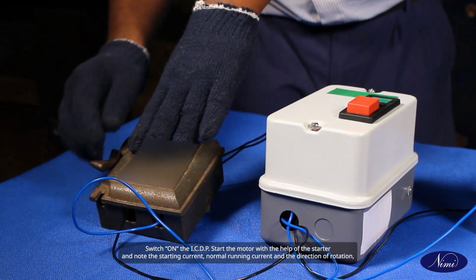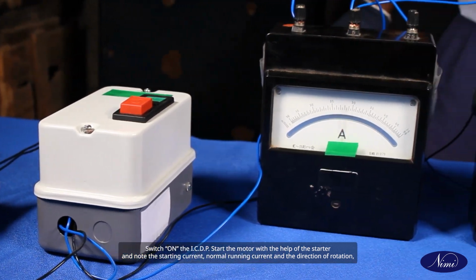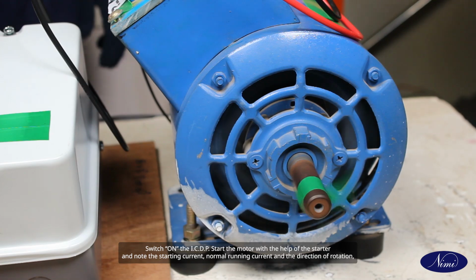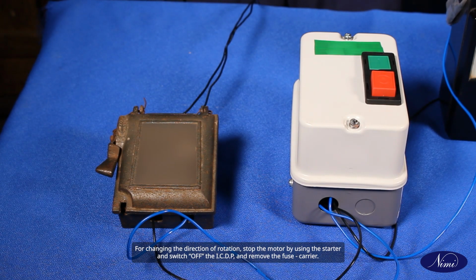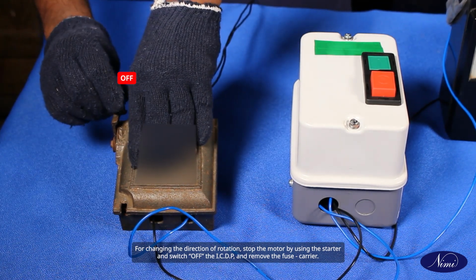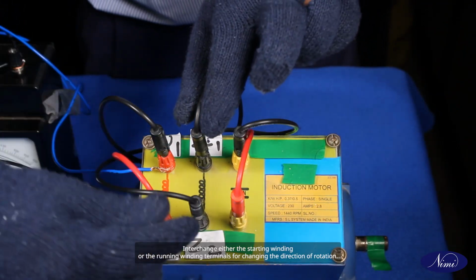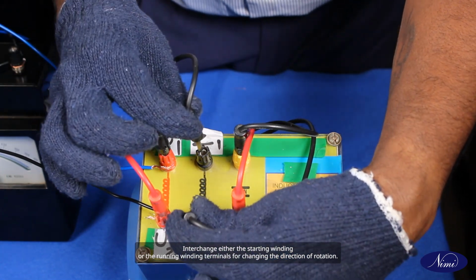Switch on the ICDP, start the motor with the help of the starter and note the starting current, normal running current and the direction of rotation and enter the details in tabulation. For changing the direction of rotation, stop the motor by using the starter and switch off the ICDP and remove the fuse carrier. Interchange either the starting winding or the running winding terminals for changing the direction of rotation.